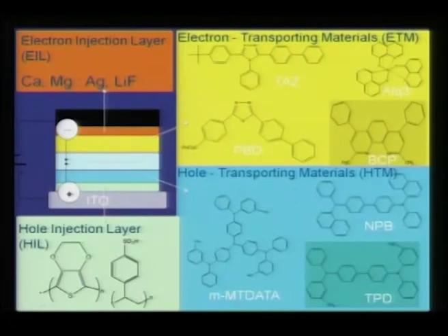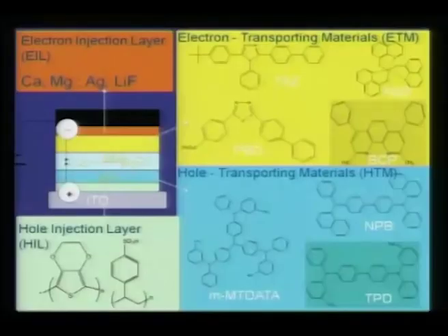So, this is the most popular, or billion-dollar molecule, so to say, which is controlling optoelectronic applications as of now, but there are several such molecules being generated. We are going to see in the next few lectures a special study on this AlQ3 and several other molecules which really govern the organic displays. Having said that, I have been talking to you more about AlQ3, which sits in this place in the device, but there are several other organic molecules which add to the complexity or simplicity of this device. As I told you, you have a HTL, that is hole transport material, and you also have an electron transport material.